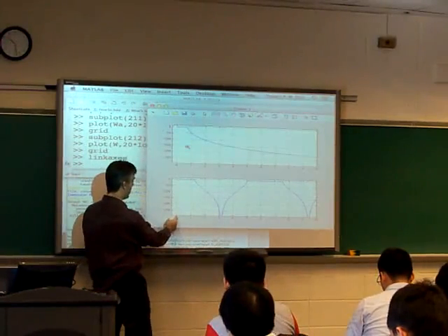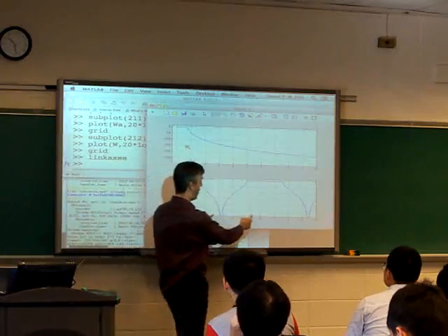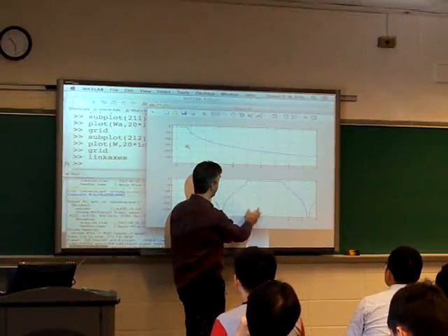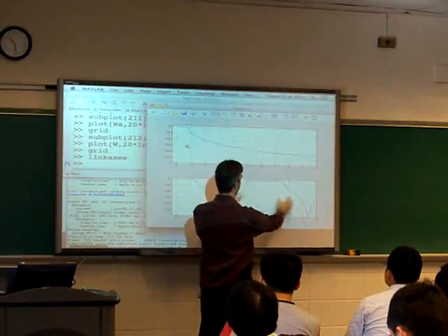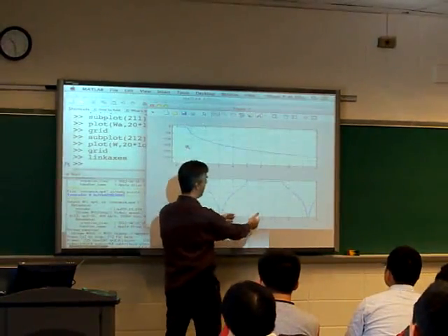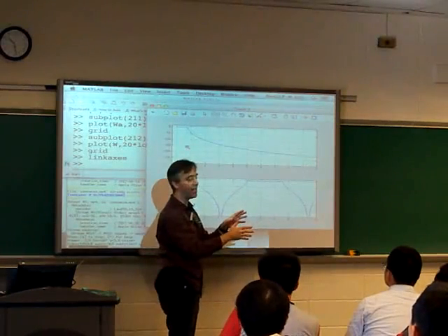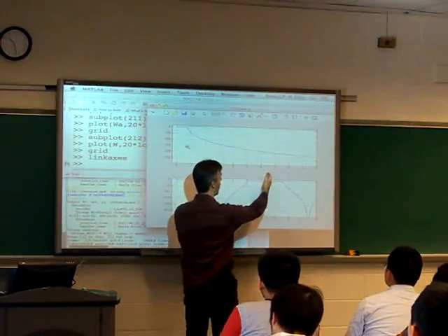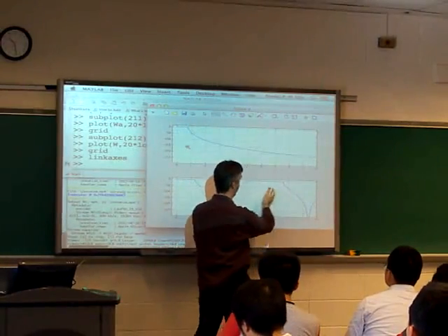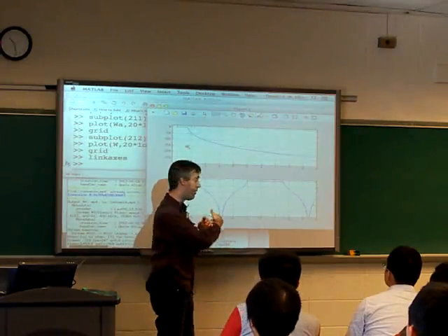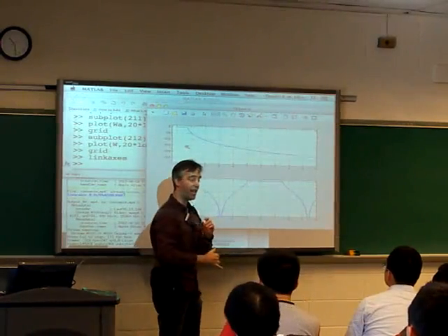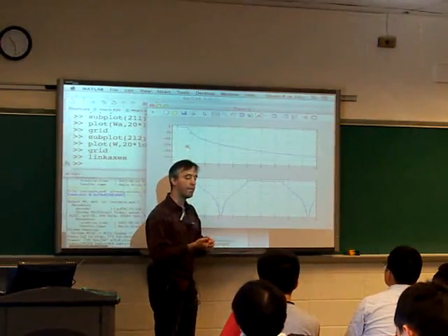Because of the periodicity, this chunk of frequencies here is going to show up here as well, leading up to 2 pi. So this symmetric response, which is what it would look like if you plotted it around 0, you've got to have that if you want a real-valued system. We could try and build a filter that only let through positive frequencies and had 0 for negative frequencies, which would give us 0 values in here. But that would be a system that had a complex impulse response.